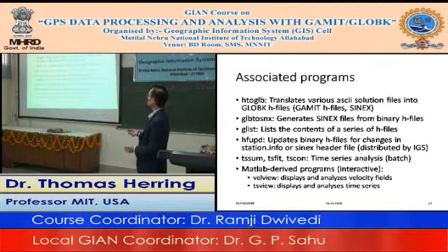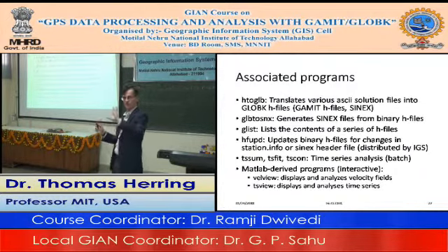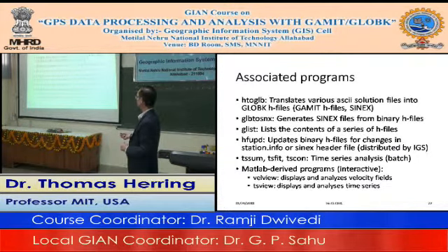So, the associated programs with GLOBK. H2Global we've already talked about. It does the conversion. Global to SINX is the inverse. It generates SINX files from binary H files. So if you want to share your results with someone who maybe used Bernese, you can send them a SINX file out of GAMIT, and they should be able to use it, hopefully. GLList lists the contents of a series of H files. HF update updates binary H files for changes in station.info or the SINX header information distributed by that. But again, it's really for antenna height changes, not antenna type changes.